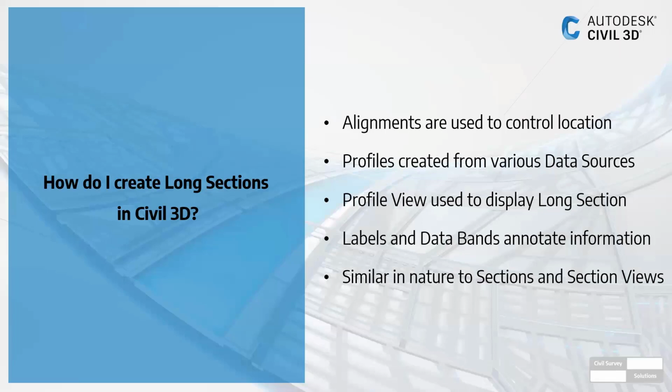Profiles are generally made from a variety of sources. Primarily, you would use terrain model information for your natural surface, or perhaps a design surface or an intermediate surface if you wanted to reference it. And then your actual design profiles are your vertical gradings, basically your vertical design of whatever it is you're looking to model. The profile view is what you use to show it in the drawing. Because you can make all these objects and they live as part of the drawing, but until you insert a profile view to display it, you can't really visualize it and see what's going on.